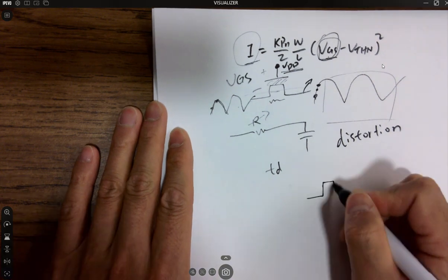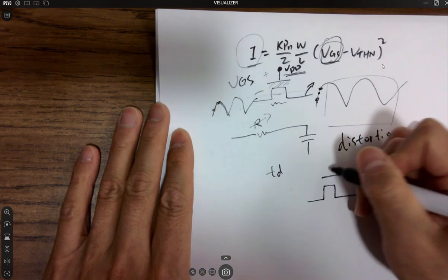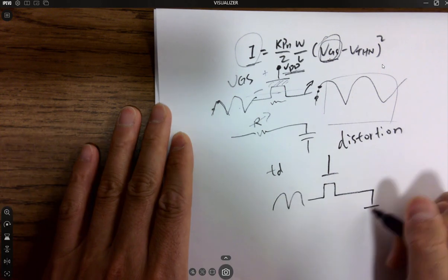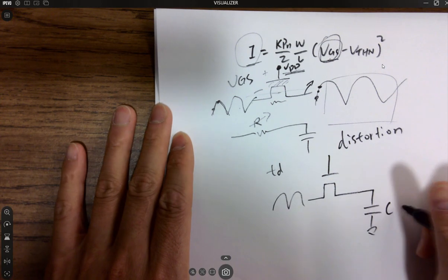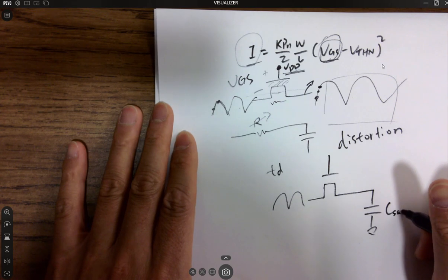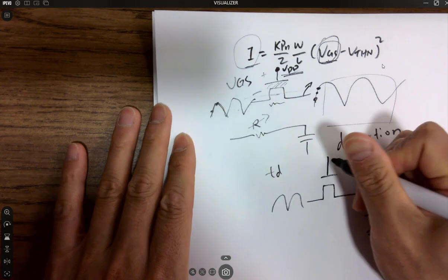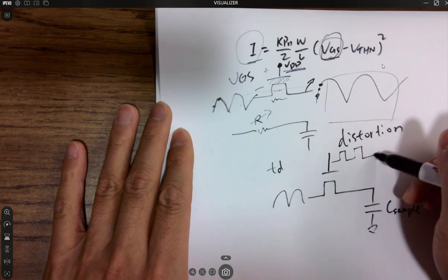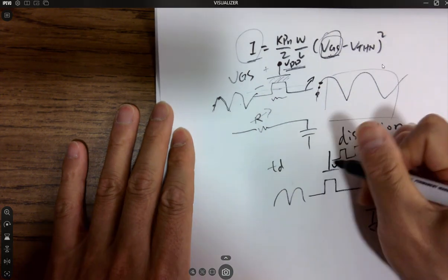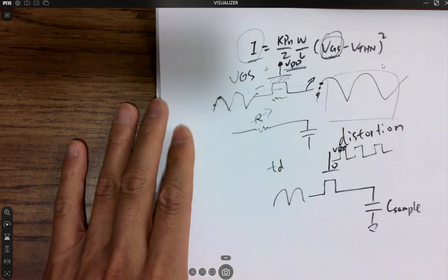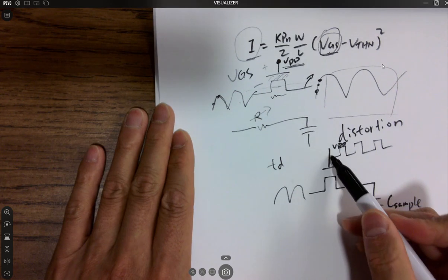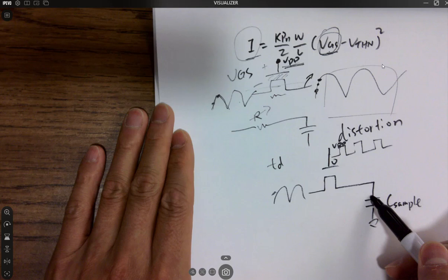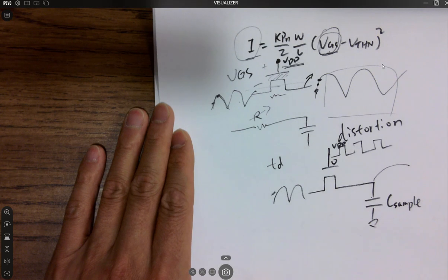And here, if we don't have that complicated circuit from the paper, right? Analog signal comes in, I got a capacitor, like C sample. I turn on this one, right? I can turn on and off. I control this one from 0 to VDD. If I want to sample it, I turn on this NMOS transistor and I sample a point to the capacitor, right? And then I read it out.